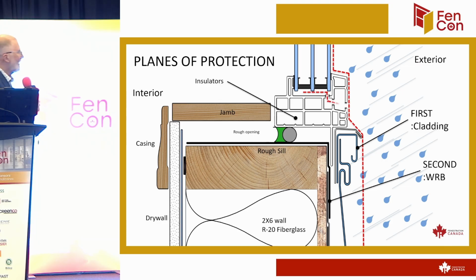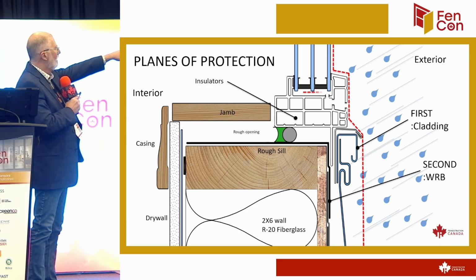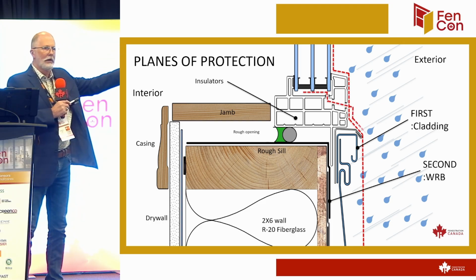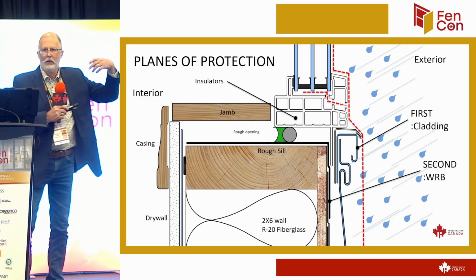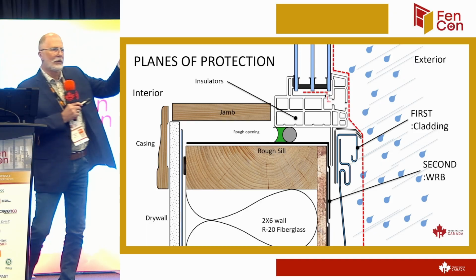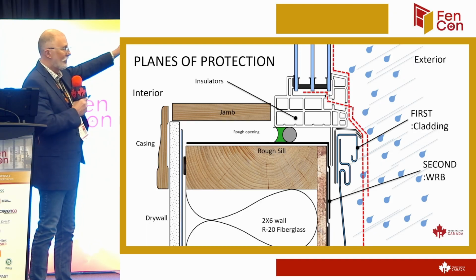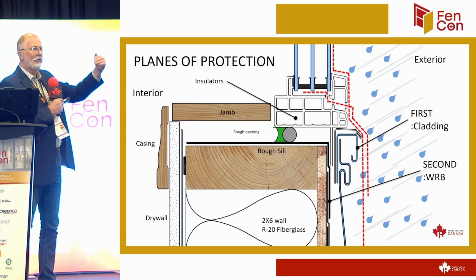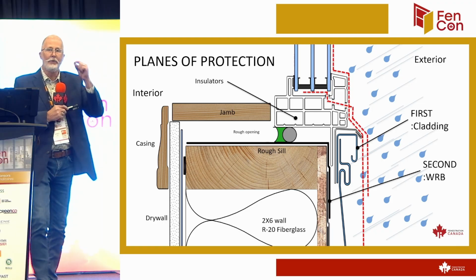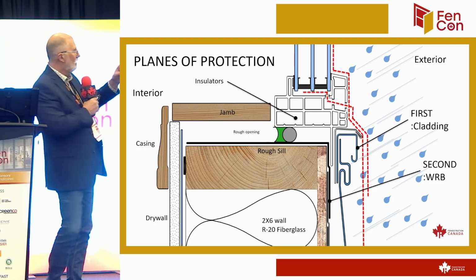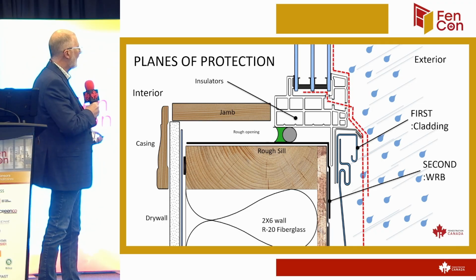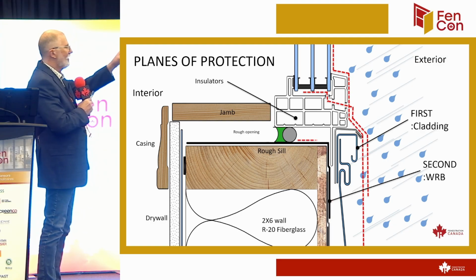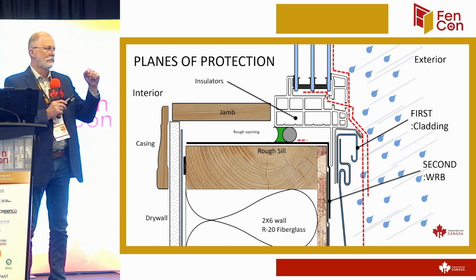Then we also have a secondary drainage in the window itself. So a lot of people don't realize that windows need to drain excess water that gets in there. Sliders and casements, not so much pictures, but a lot of windows have to have this internal drainage system so whatever water gets in there can safely leave and drain back outside. Well, that same principle is what we need to apply to the rough opening, because the rough opening is going to get some water in there from some source. Is it able to freely get rid of it?